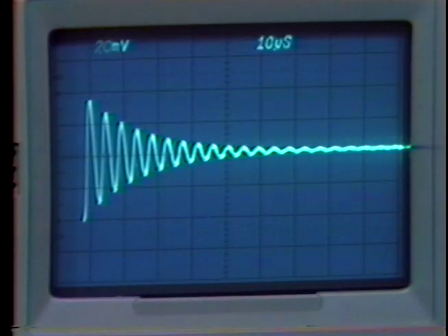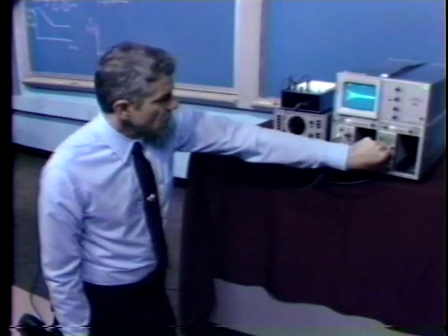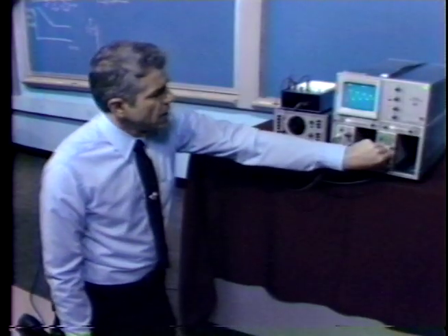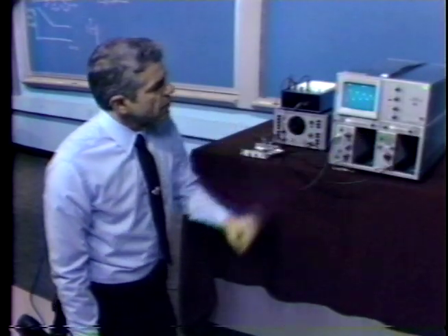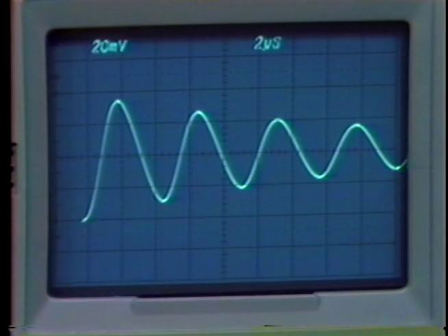So the settling time of this amplifier has deteriorated to more than 100 microseconds with the addition of the 1/10 microfarad load capacitor. We can also notice the ring frequency. We're now at 2 microseconds per division, so the ring frequency is somewhere in the order of 200 kilohertz for this particular amplifier.